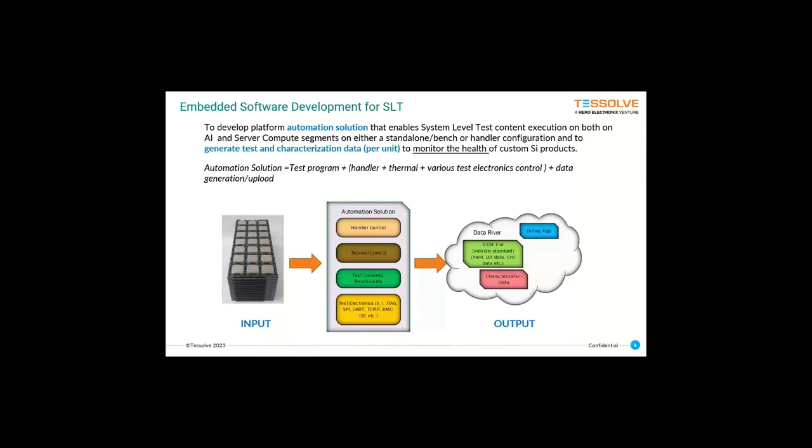Normally, if all test cases pass, the chip goes to the pass bin and then goes for release. There are a few chips which fail also. Those go to the fail bin, and for the fail bin we also need to identify why it failed. What is the real reason for failure? There are logs captured for each and every test case, and the sequence is also captured, and with this it is easy to identify the real cause.